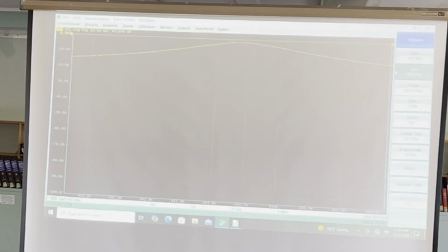You see now we have a much broader display, because we're spanning over 442 to 445. So all of a sudden now that peak doesn't look as sharp as it is, but it really is. I mean, that's the bandwidth. But look, it's already down 3 dB at, if it's 725, let's put a marker in here. You can add markers, and there's 443 and a half. That's where you see the number 1. So let's grab this marker, and let's move it where I think the peak is, which is about there.